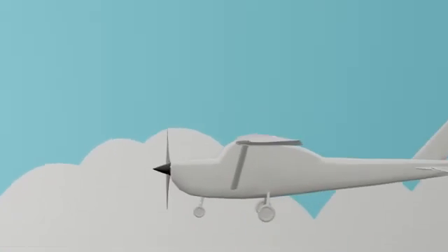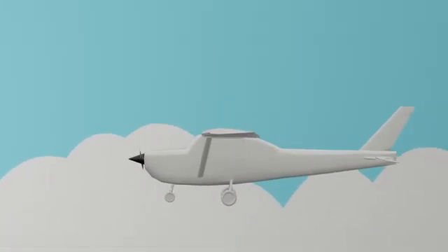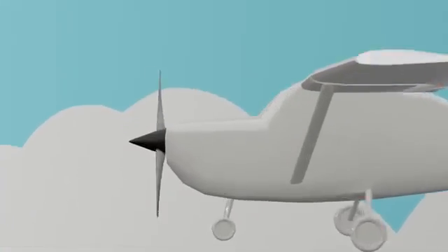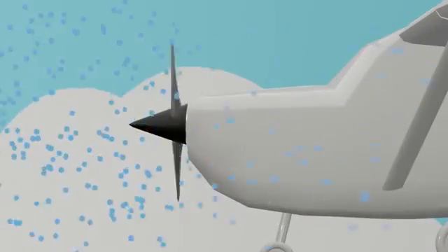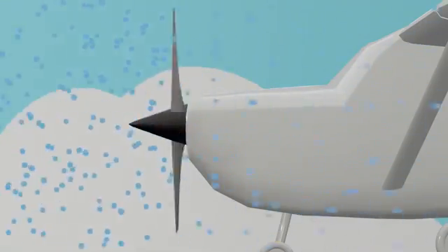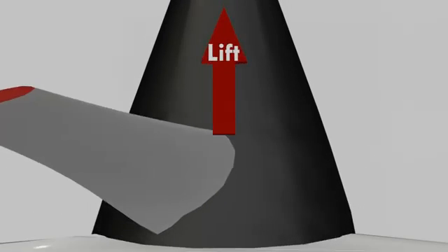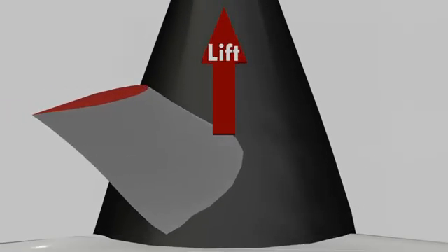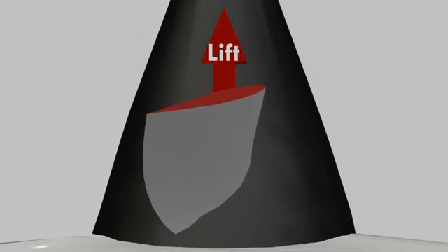Before we consider how our new constant speed propellers work, let's review the fixed pitch variety first. Propellers are the way which engine power is converted into thrust, accelerating air backwards, pushing the airplane forward. How does it do this? Well, propellers are just wing blades on sticks. The lift force of the blade, turned 90 degrees, is the airplane's thrust.